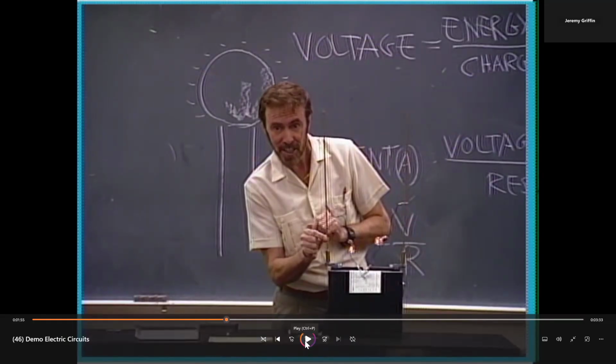All right, so guys, if you don't get everything today, just pay as close attention as you can, think as deeply as you can. But you guys see how voltage drops down a little bit at a time? I'll make an analogy. Voltage is kind of like elevation. What if you have a series of waterfalls, one after another? So it's like it dropped 6 meters followed by another 6 meters. We drop 6 volts followed by another 6 volts to add up to the 12-volt battery. Okay? But the current, guys, there's only one street for the current to flow, so the current's the same everywhere.